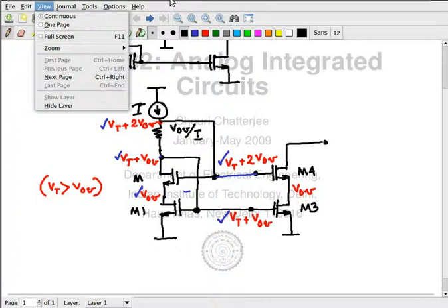Okay? If you try to make a specific value, the tolerance of it is something like 20%. So you have to build in that margin onto that resistor. You have to make sure that you accommodate for that 20% variations here and there. That's basically the balance. This would be made with polysilicon or some material, not with the MOSFET. Area will also be high, depending on the value of the resistor.